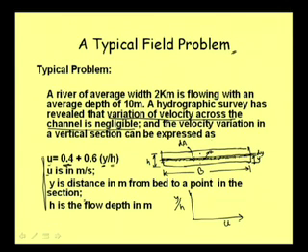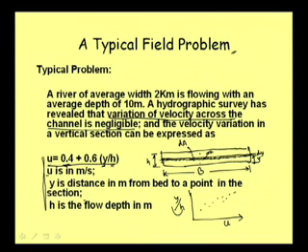And when we are on the surface, then say y becomes equal to h. So, h by h becomes 1, and then the velocity becomes 1, 0.4 plus 0.6 equal to 1. So, by putting this value and that value, we may get some points, and when we relate these points we will be getting a straight line. That means we can approximate this by a straight line, because we can see that this relationship is linear, this velocity is varying linearly with y.